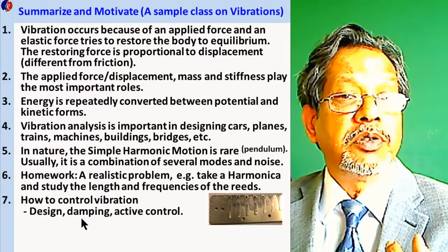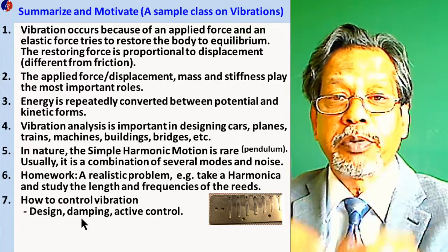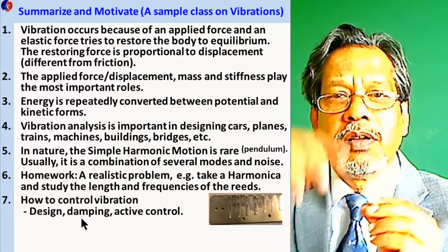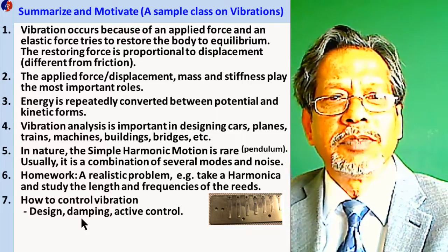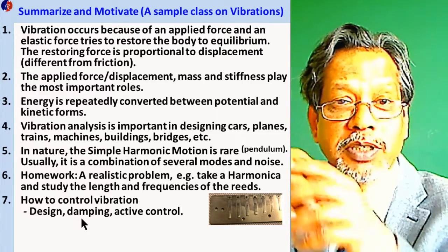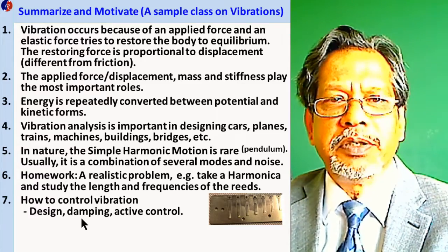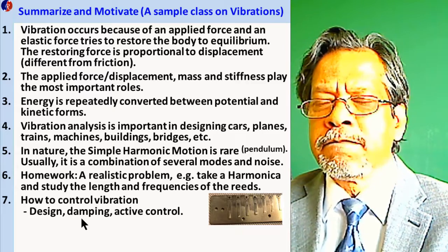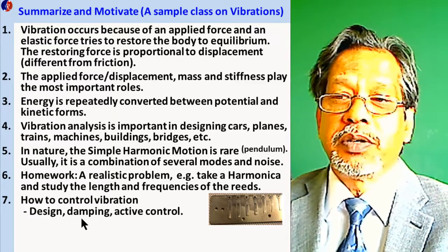Damping: you can introduce something called damping. Some of the cylinders with liquid are dampers. For example, car suspension has a spring, either a coil spring or a leaf spring, and dampers. Sometimes dampers and springs are built into one system. They use viscous damping. One could probably use frictional damping too. A damper reduces the vibration.